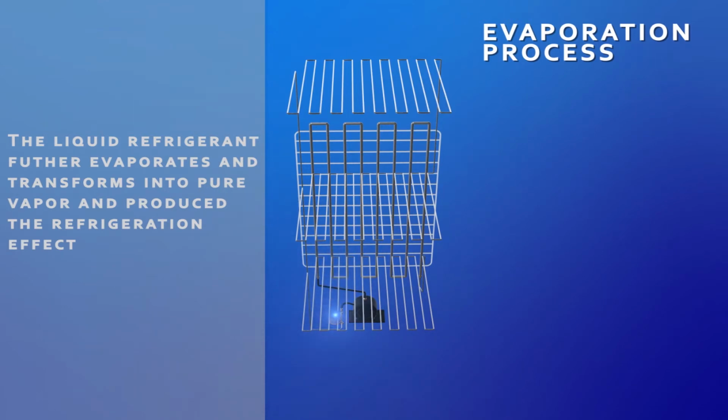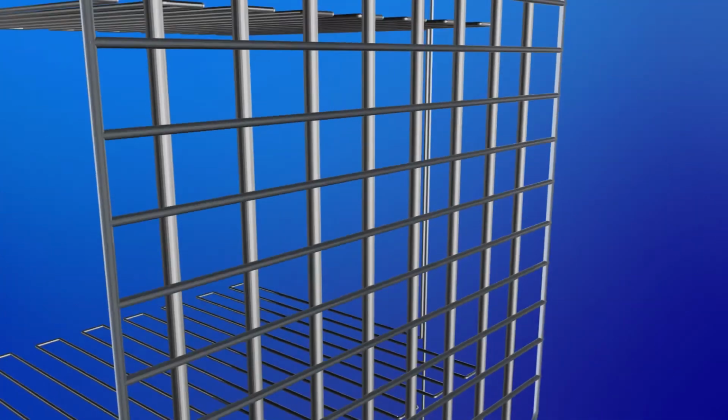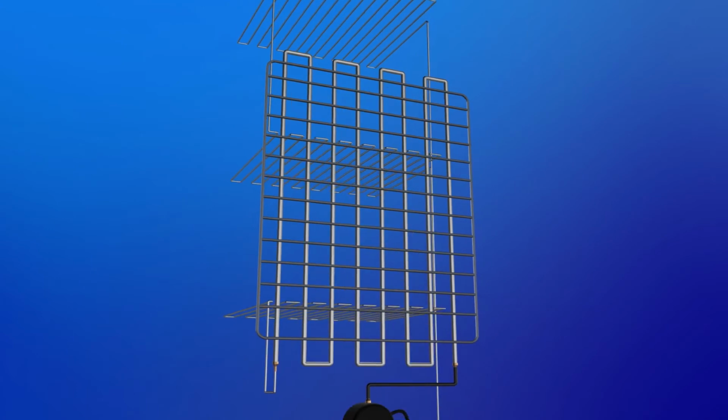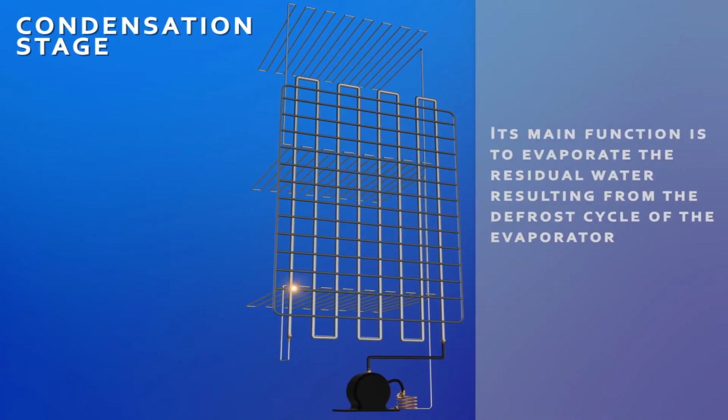Ice buildup caused by the humidity in the air and deposited in the evaporator will significantly reduce the performance of the whole system. Bundy evaporators are designed to delay ice buildup, which reduces the frequency of defrost cycles, thus reducing overall energy consumption. During the condensation stage, latent and sensible heat are rejected to the environment, while the refrigerant suffers a series of phase changes.